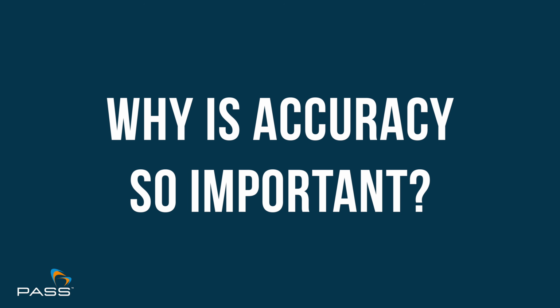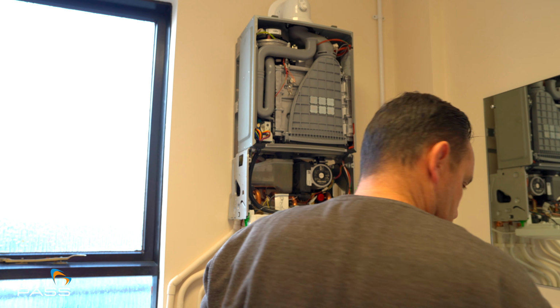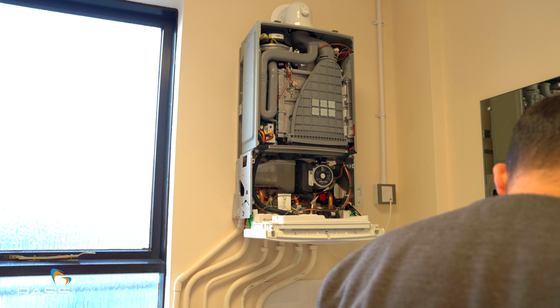Okay. If thinking about how a boiler is being set up, the key things for an engineer setting any boiler up is: is the boiler safe? You've got to make sure that obviously all the products of combustion are being put through the flue. It's understanding of the measurement being taken to guarantee that, but also it's the whole aspect of making sure the boiler is set up to be its most efficient.